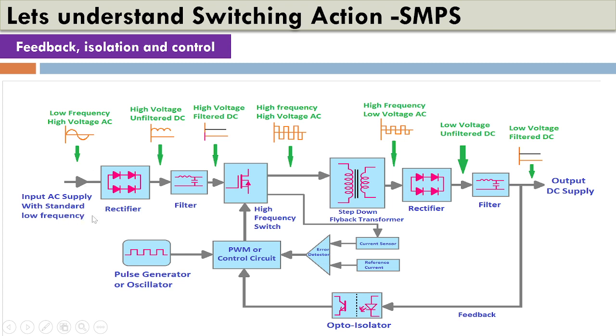The input line gets rectified by the power diodes, filtered by the capacitor, and after smoothing it out, it is applied to a circuit where we have a transformer directly connected to a switching transistor, on the primary side.